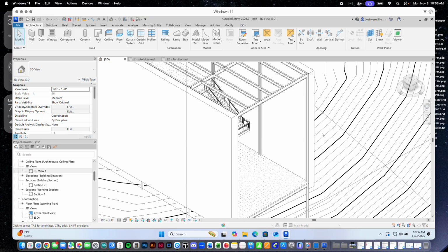Now, if you don't believe me, have you guys ever been in your studios in the morning time? Those aluminum frames with those little skinny tall windows start to creak and crack because the glass and aluminum expand at different rates with the masonry opening for each one. When the sun's in the east, especially in the morning, and starts to hit it, it heats up that east wall. You start to hear crackling and popping, right? You'll hear that a lot in curtain walls.